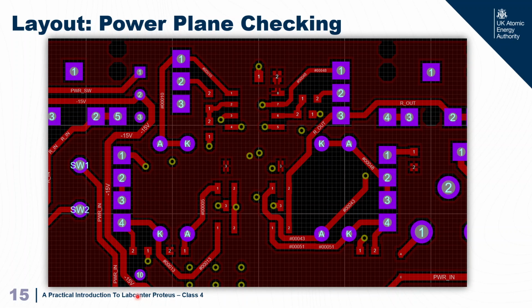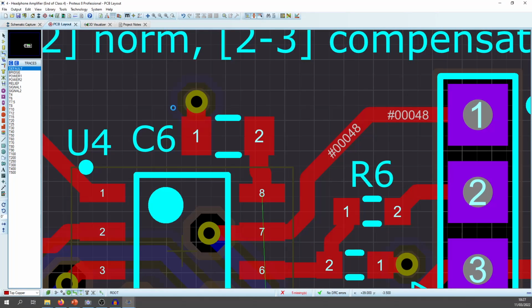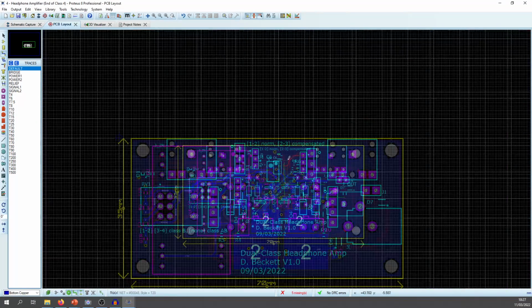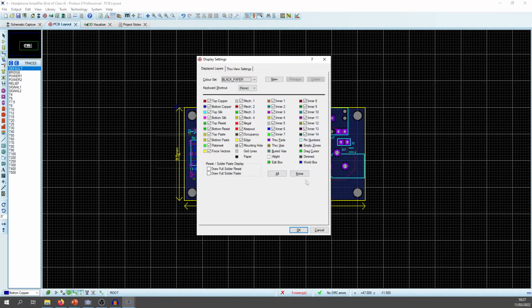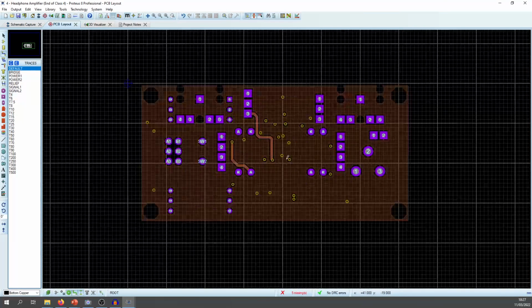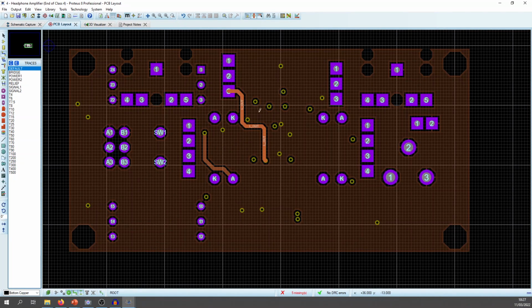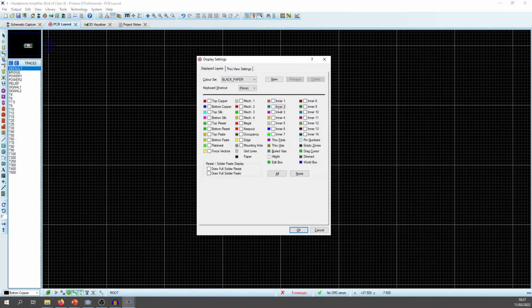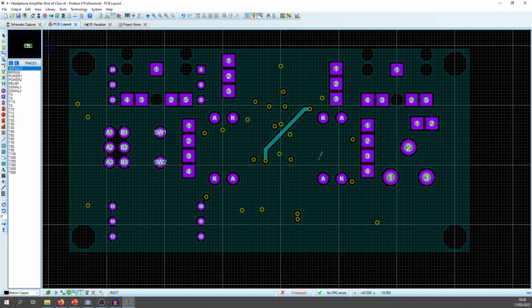So I moved that trace off that layer, and I actually used one of the internal layers. Another point is, actually, whilst we're here, on the internal layers, you want to keep them as solid as possible. So I've put a couple of traces on that layer, and these are the ground planes. And I've put one trace on there, i.e. I've not cut them up. I've kept them as solid as I possibly can. That's an important part of good design, especially for EMC.